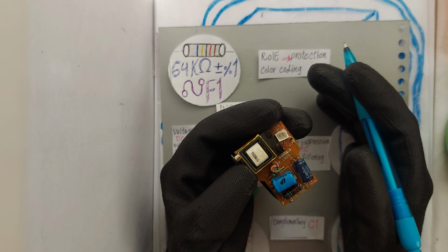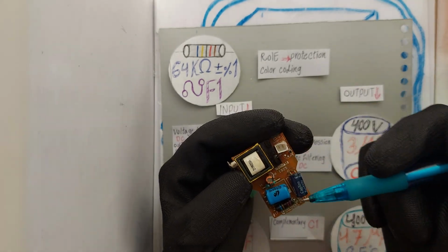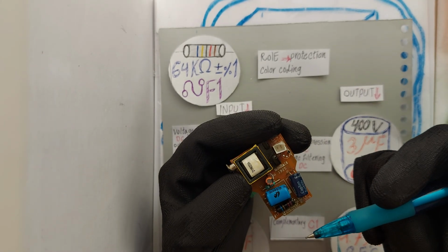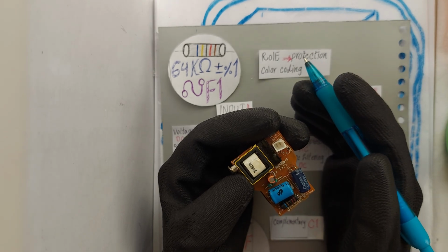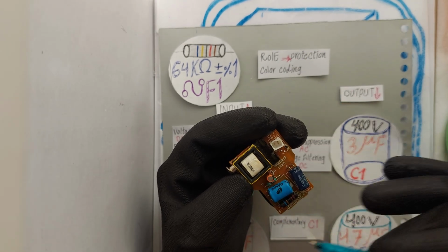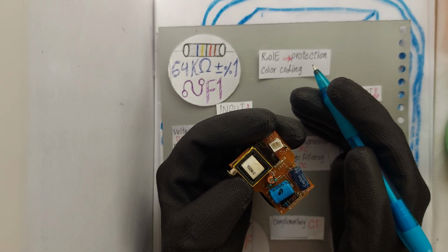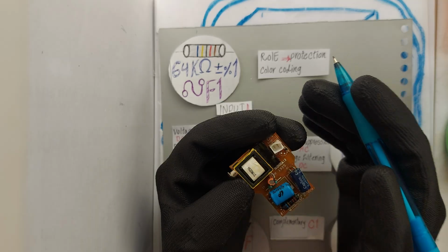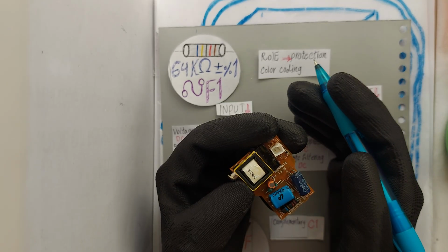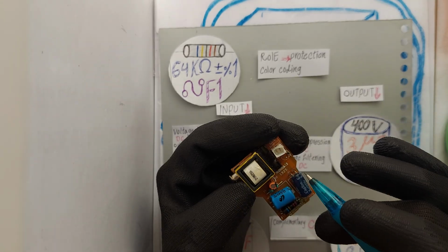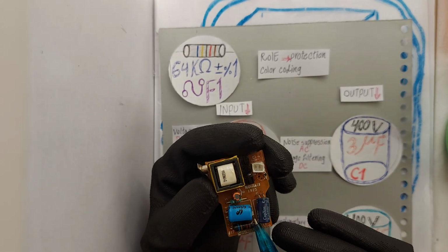In this charger board, the F1 fusible resistor is located at the AC input near the diode bridge, and its job is to protect sensitive components like the diode bridge, transformer, or capacitors from overcurrent or voltage surges. This ensures that in case of a fault, only the fuse burns out and needs replacement, not the entire board. And now color coding.